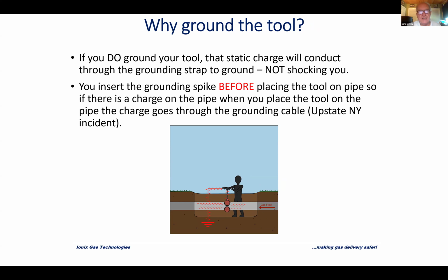And the other thing that's often asked of James and I is how thick does the grounding line have to be? The grounding strap, whatever's initially installed on the tool will be fine, as long as you maintain it and you have a good connection. Static electricity in these instances has a very high voltage, but it has no current. In other words, when it arcs, it's going to be over in a second.